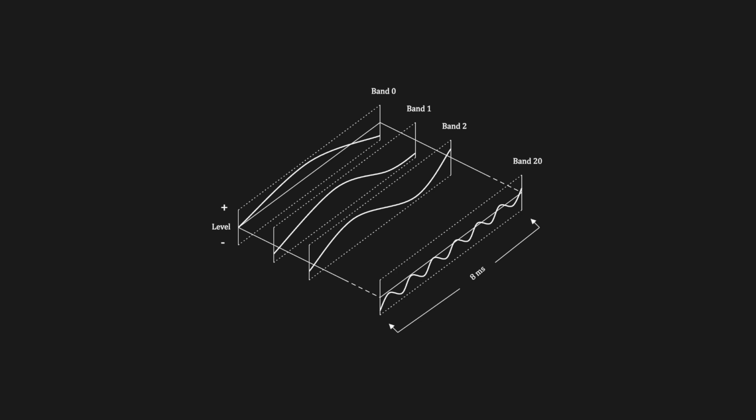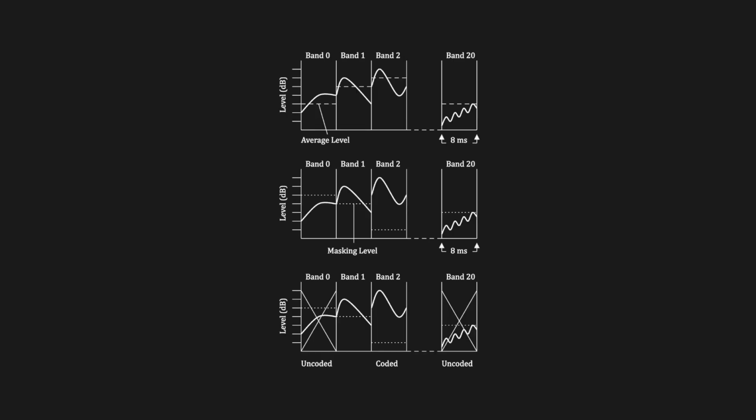The encoder then applies a psychoacoustic model to calculate a masking curve that defines what parts of the sound are audible. The energy level of each subband is measured to see which ones contain audible content. Then, the average power of each subband is compared with the hearing threshold, giving the final masking level. Any subband with sounds below this level isn't coded. Similarly, tones that are hidden by louder neighboring tones or entire subbands masked by others are skipped to save bits.